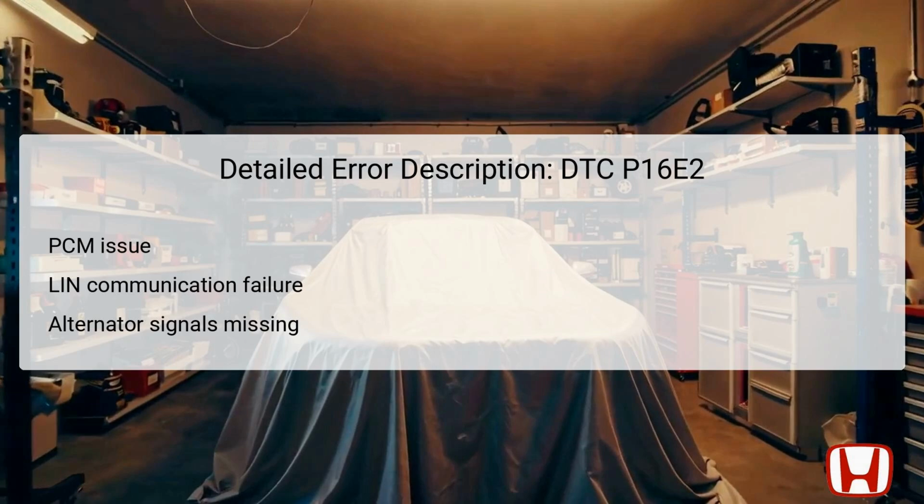LIN. This error might occur if the wiring harness connected to the alternator has loose terminals or if the LIN communication line is interrupted. Locating the affected components is vital, primarily focusing on the alternator's +B terminal, the PCM, and any connectors associated with the LIN. Any malfunction in these parts can disrupt communication, ultimately triggering DTC P16E2.